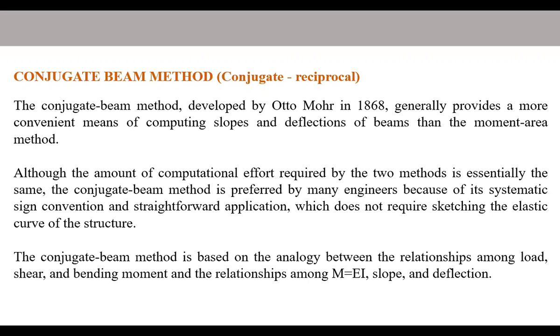When you work out these problems, you define support conditions, E values, I values, and very often a lot of people make a mistake in exams: when you define an I value in the wrong units, you will get wrong results. Sometimes you will get a deflection like 50 meters, which is about the height of this building. Okay, that is not possible. So that is why we are doing so many methods.